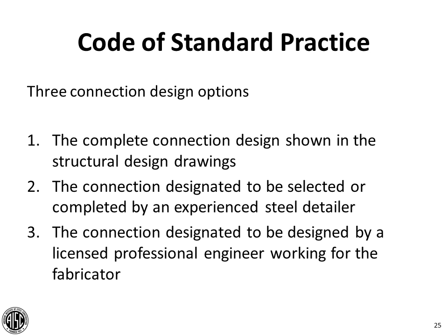However, I personally have been involved in projects where all of the connection design has been delegated, even where there's high seismic requirements. So the first option is that the engineer of record completes all of the connection design and shows it on the structural design drawings. So essentially everything's engineer mandated at that point.